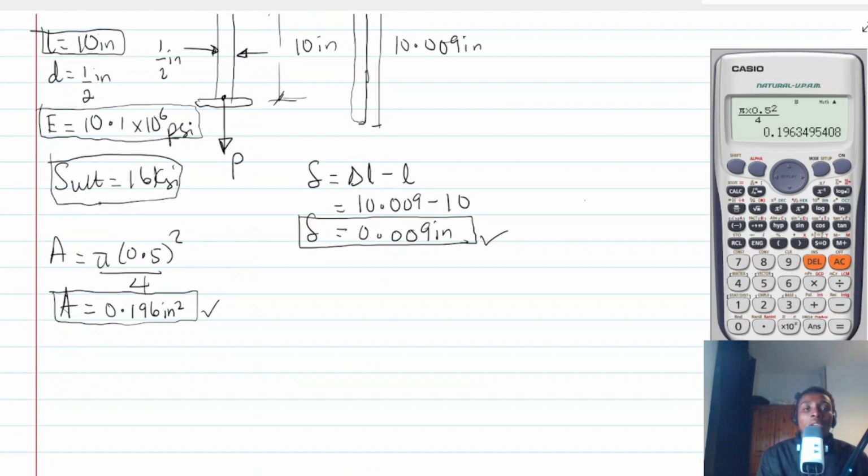E is here, L is here, and we want the stress. So this is PL over AE. We know this, but we don't know the load.